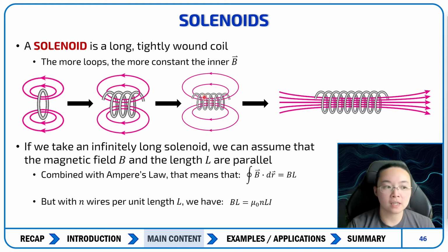So as we extend the coil from here towards this, the longer the coil, the more the magnetic field is forced to have a larger radius of curvature so that it can go along and exit along the edges of that coil. That forces the center of the coil to have a more linear and constant magnetic field.